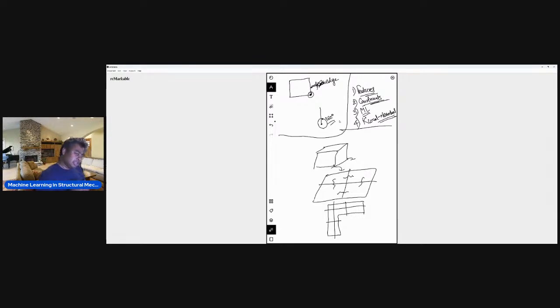But again, these possibilities are where you are looking at unassembled matrices, and I showed you some examples of unassembled matrices, how the displacements match, how the stiffness matrices match. And basically once the stiffness matrices and displacements match, of course it's a done deal. But then we also went ahead and showed you not only that, but the eigenvalues match as well. So those are important pointers. On top of that, we also talked about how to look at different features of certain elements.